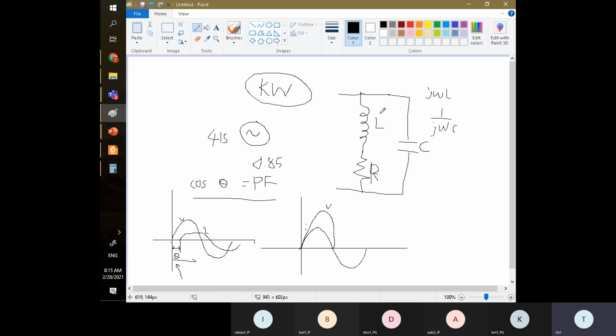So when we have this inductive problem here, if we add a capacitive load in parallel to the load here, actually we can bring the voltage towards this direction, so that they are kind of close to each other, because this capacitive will make the voltage lagging. So when initially we have the current lagging, if we can make the voltage lagging also, hopefully they can align again. So this is the only solution to this power factor issue.